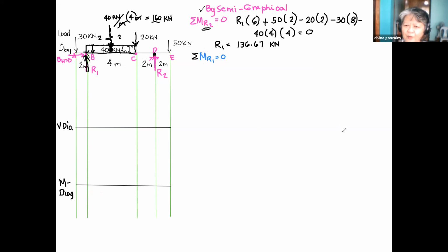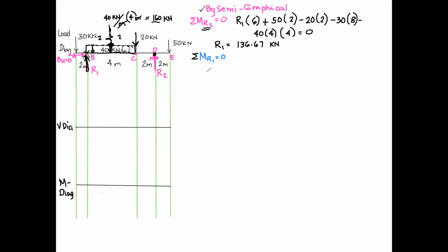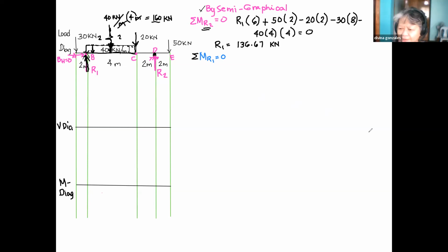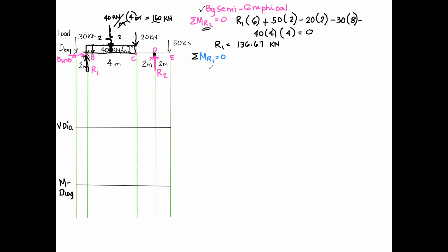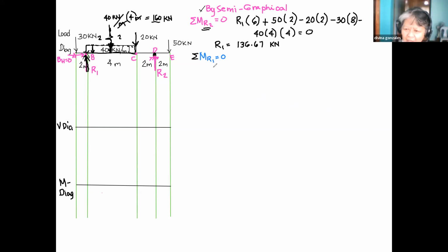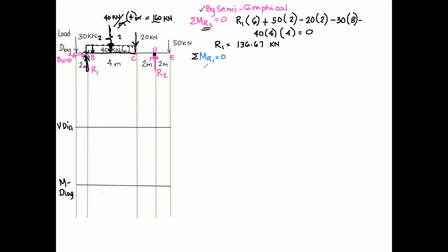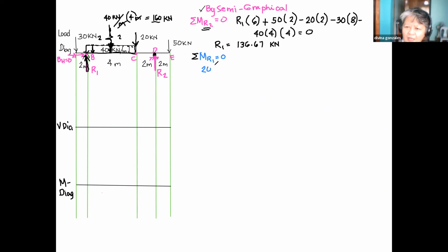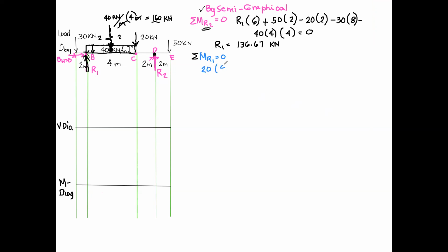Okay? So, sum up moments about R1. What are the forces having moment about R1? Bautista, are we waiting for you? Sorry, ma'am, I'm not ready po. Counterclockwise po is the 30 kilonewtons. Will you kindly start with clockwise first? Okay po, 20 kilonewtons. 20 times what is the perpendicular distance? 4. Okay, is there more?